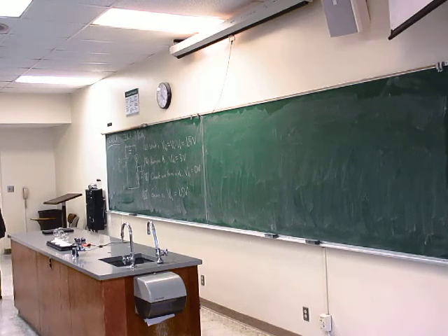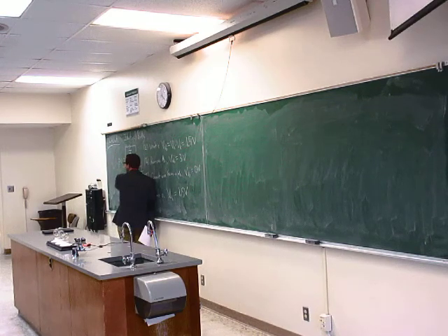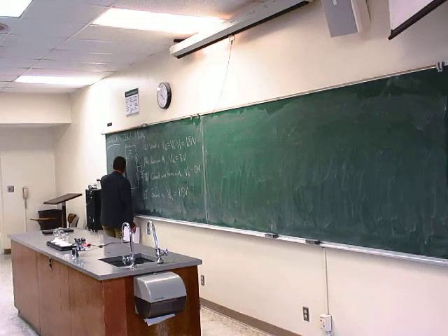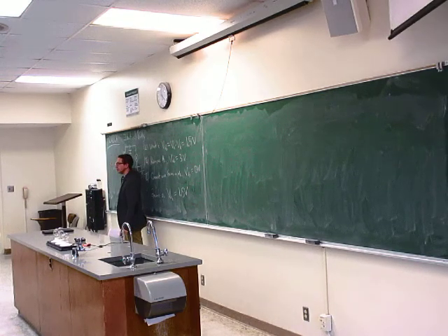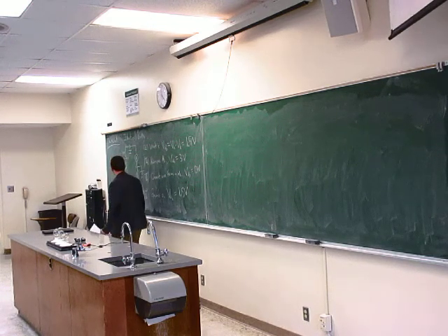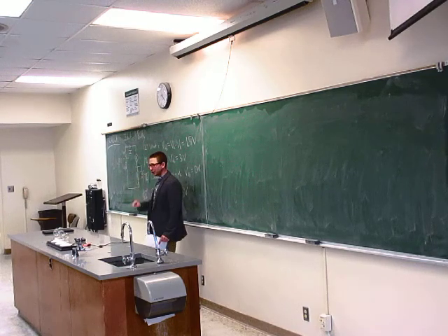What did you say was negative 1.5 volts? Oh, so B would be at negative 1.5 volts. A would be at 0 volts. Up here would be at 1.5 volts. Because it's going to drop 1.5 and it's going to drop another 1.5. So technically, our battery now would look like this: negative 1.5 and 1.5. Right. The potential difference is still 3 volts. Right? But it's not going from 0 to 3. It's going from negative 1.5 to 1.5. And that's why normally we're just dealing with potential difference, but when we set a ground, we're saying where is the 0 point for electric potential in the circuit.